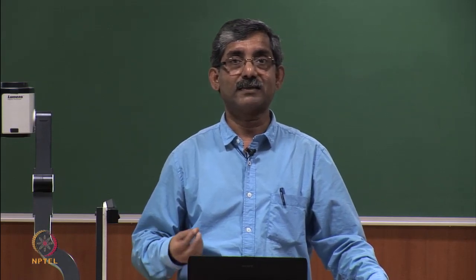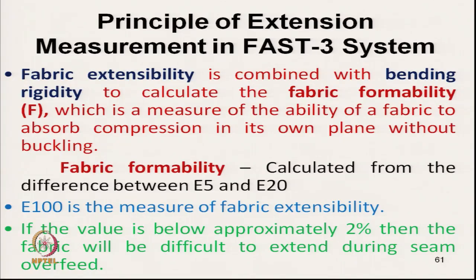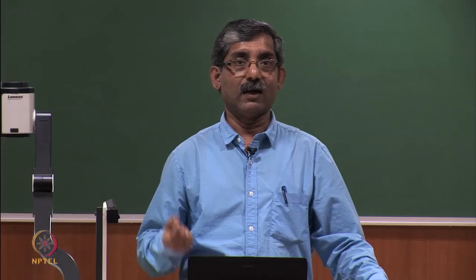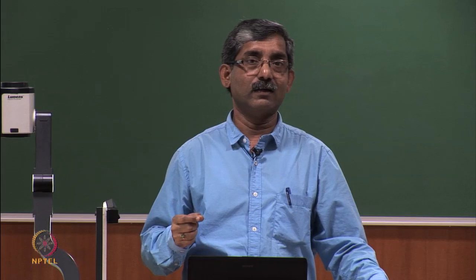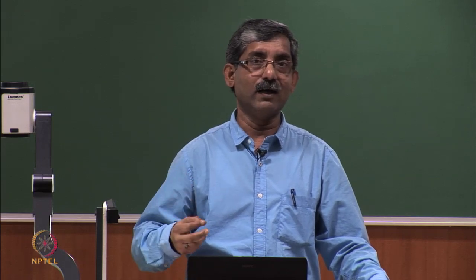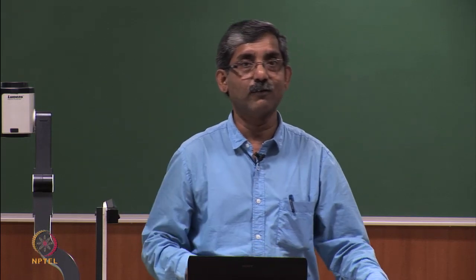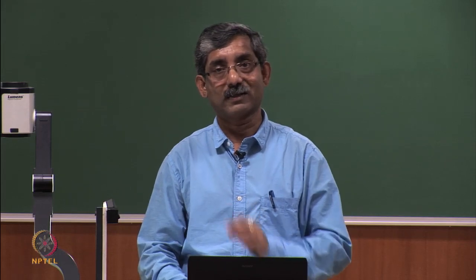fabric extensibility. If the value is below approximately 2%, then the fabric will be difficult to extend during seam overfit. So, that will predict the sewability of the fabric, and E100 will also give an idea about the stretchability of the fabric at lower extension.